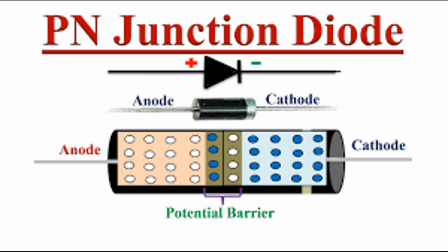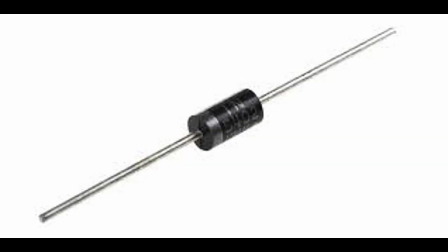Voltage clipping, also known as amplitude clipping, is a signal processing technique that uses diodes to limit the amplitude of a signal by clipping or chopping off portions of the waveform that exceed a certain voltage threshold. This technique is often used in electronic circuits to intentionally distort or shape the waveform for specific purposes, such as creating special audio effects or ensuring that a signal remains within a desired range. Here's how voltage clipping works in clipping circuits using diodes.